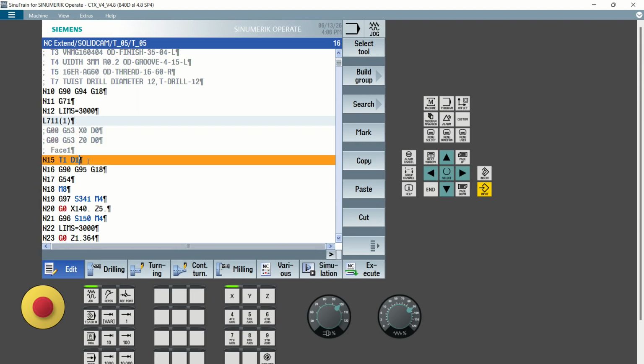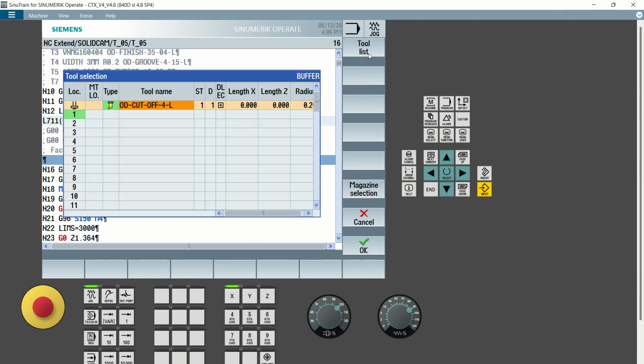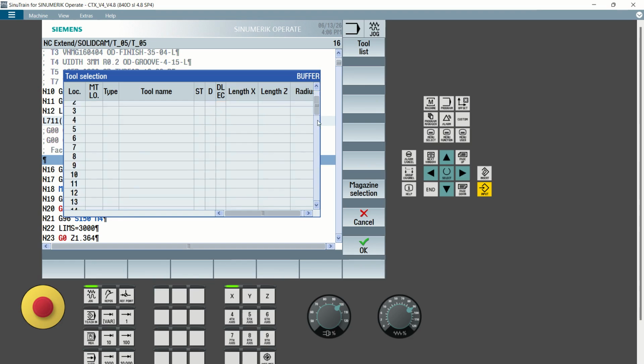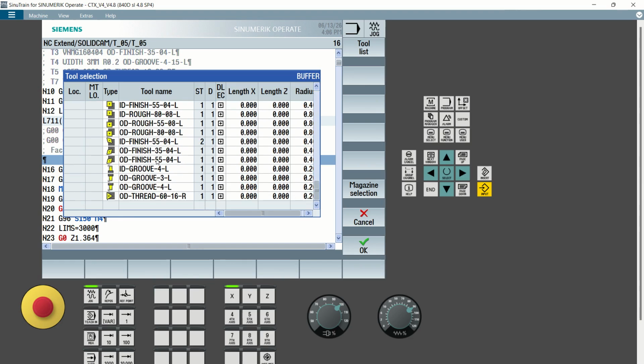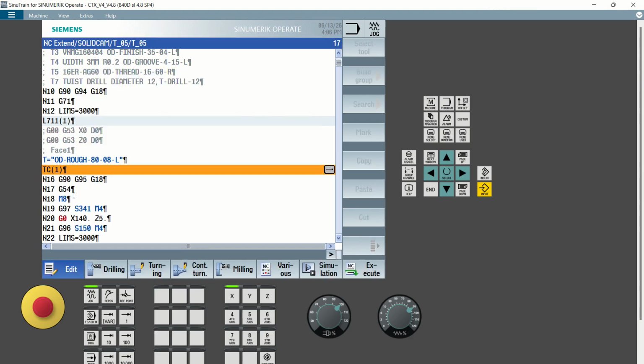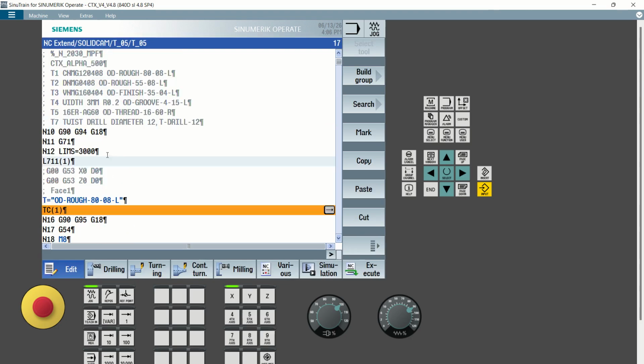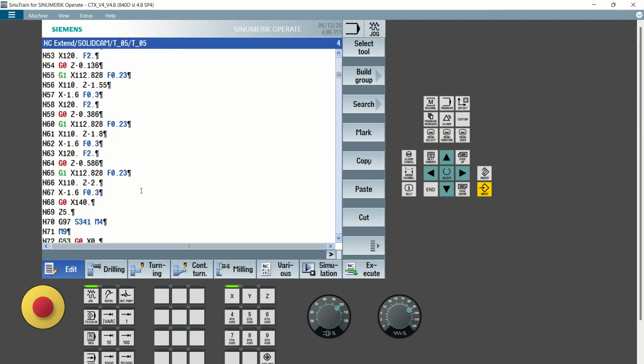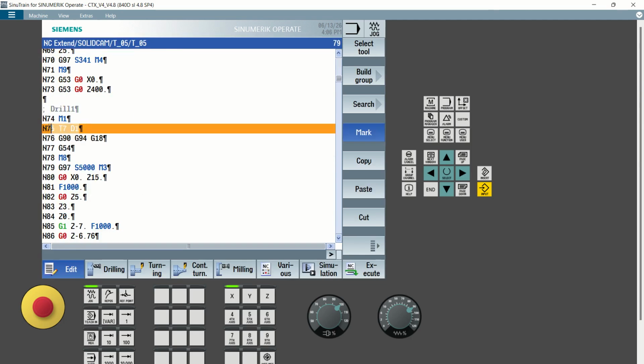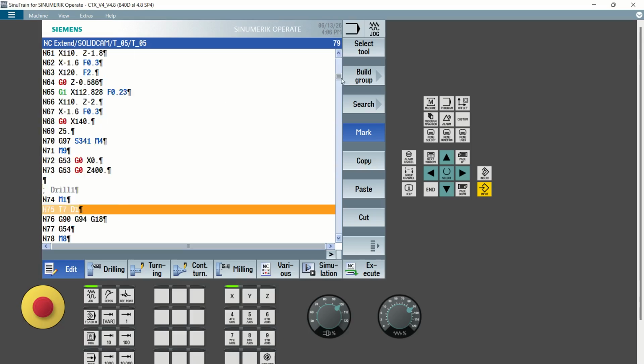Then for this tool, I need to change this tool. This is OD facing. I can now select the tool here from my magazine to just update my OD naming of tools. So see how I've named my tools. This one is for facing. Then the next, tool number 2, is for DNMG. That is OD55. So we need to use OD55, tool number 2. Let's go to tool number 2 here. You see this. I want to go one by one.